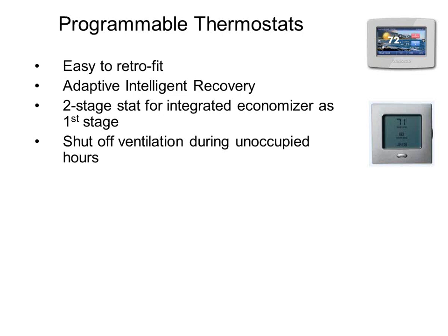You got to get a thermostat that costs about $20 more than other thermostats, and then you got to run a pair of wires from that thermostat to the economizer of the rooftop. You need a couple more wires to do this. And then whenever the thermostat goes on unoccupied, it tells the economizer damper, hey, you're also unoccupied too. You don't need to open up on these heating and cooling calls.